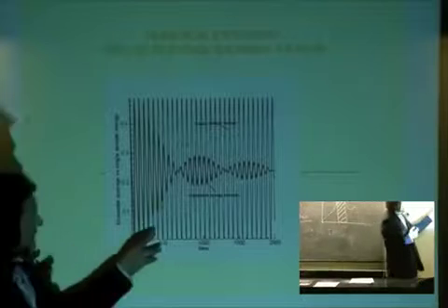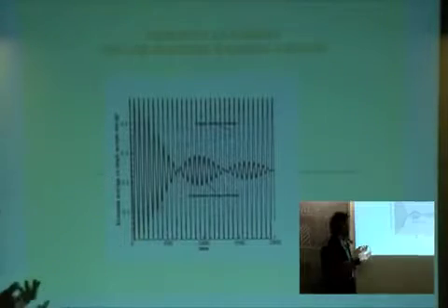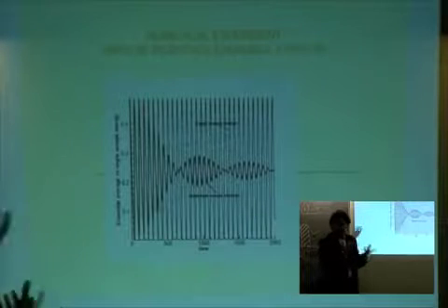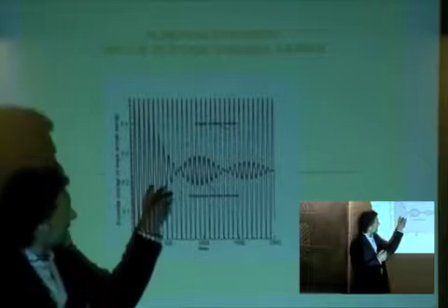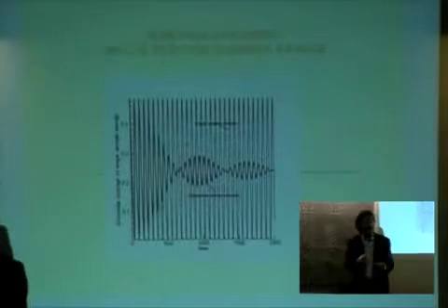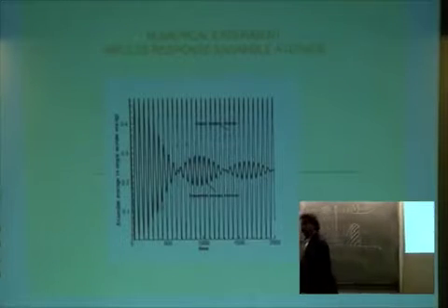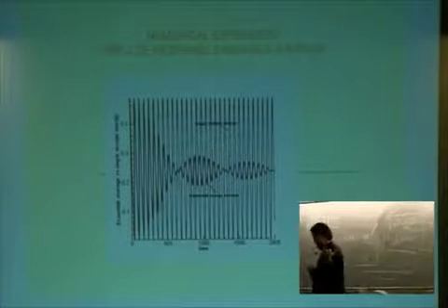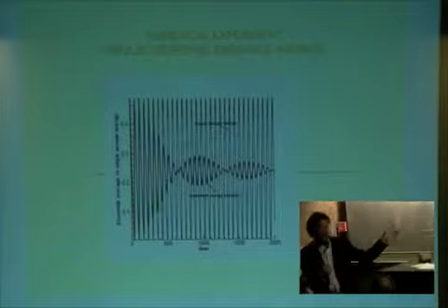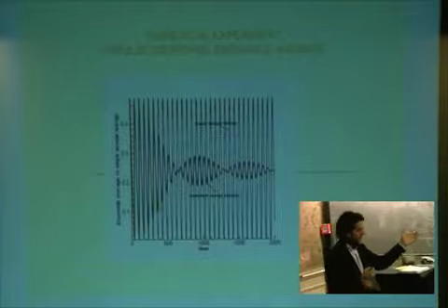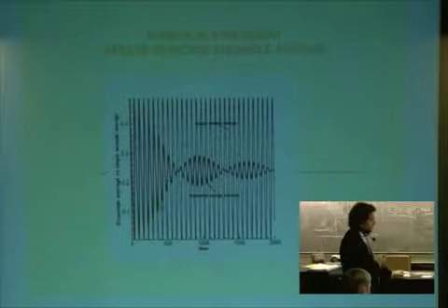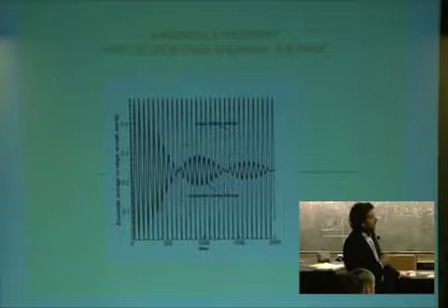It is obvious that the single sample has a periodic response. It's just a 2 degrees of freedom system. And this is the ensemble average of the 10,000 samples. The ensemble average goes to 0, while the single sample doesn't vanish as an impulse response. This is a very intriguing property.